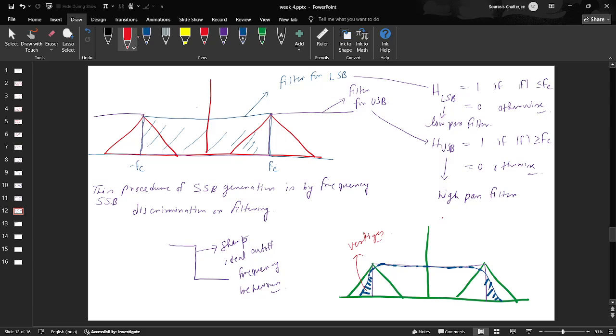So essentially, even on pen and paper, the single sideband passband frequency is FM, but in practice, since you don't have such sharp cutoff behavior, you have this additional frequency. So your bandwidth is not exactly FM, it's slightly more than FM. It is far less than 2 FM, but slightly more than FM. That is the practical behavior.